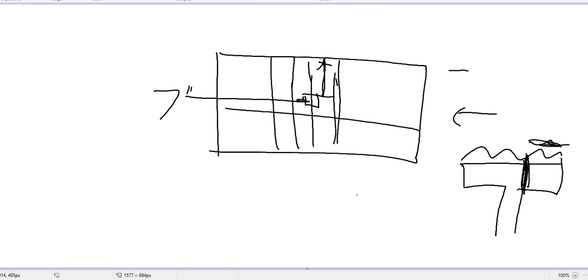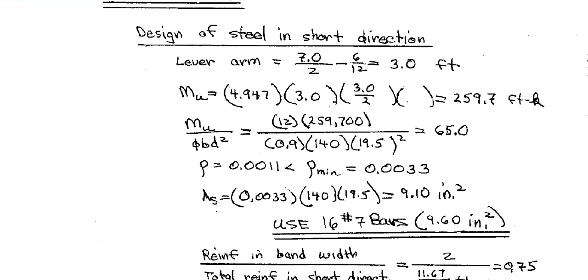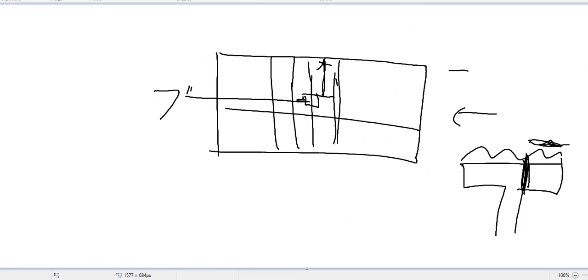So if I come to your point, yes, 6 by 12 is 3 feet. So reinforcement moment is the ultimate bearing pressure times L by 2 times your width. Now your width, can you remember what is your width? If I go back, this should be your entire width, 140 inch, or 11 feet 8 inch. This should be your width.